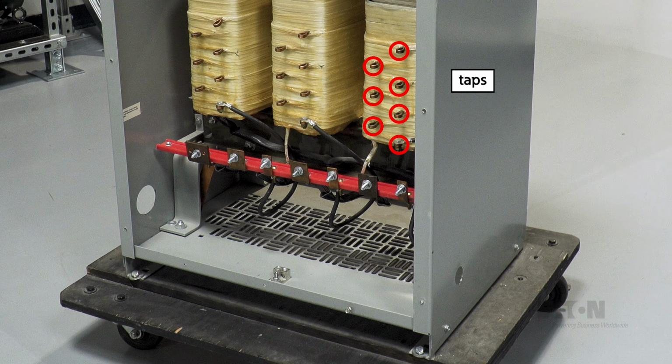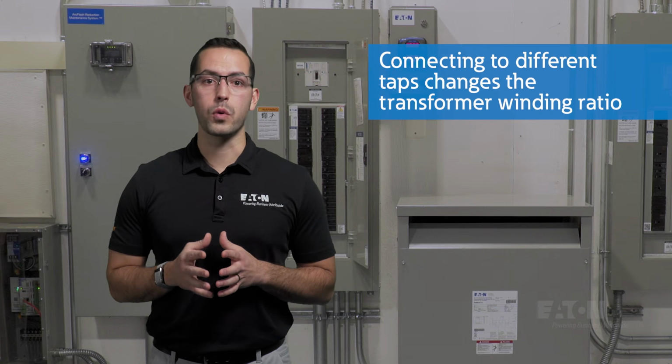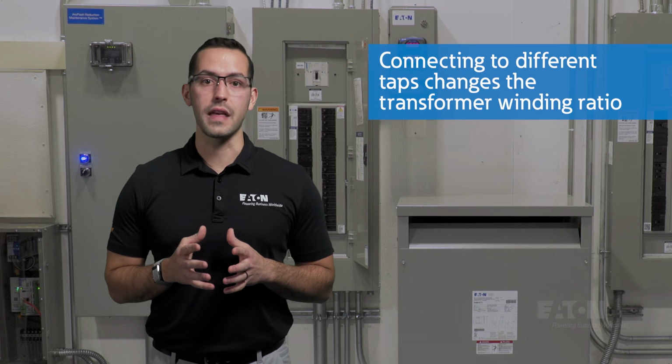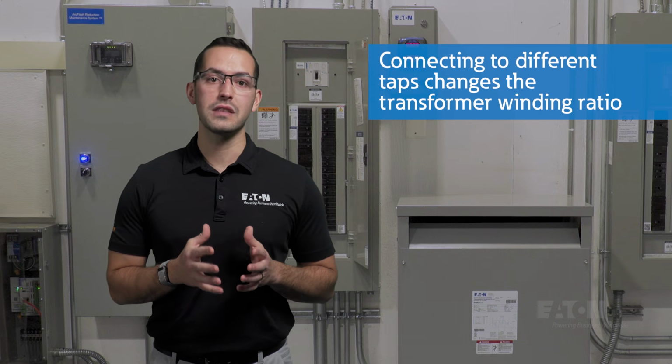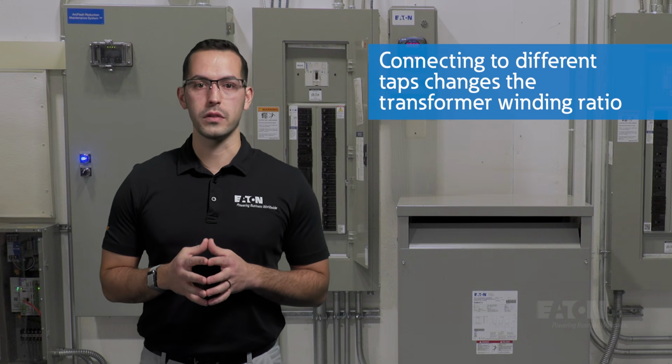Taps are the term used to describe multiple possible connections to a specific winding. This unit has primary taps that are connected at various points in the primary winding. By moving the cables and connecting to different taps, an end user can manipulate and change the transformer's winding ratio. Taps are an important component within a transformer as they allow the user to achieve their desired secondary voltage given an inconsistent or undesirable primary voltage.